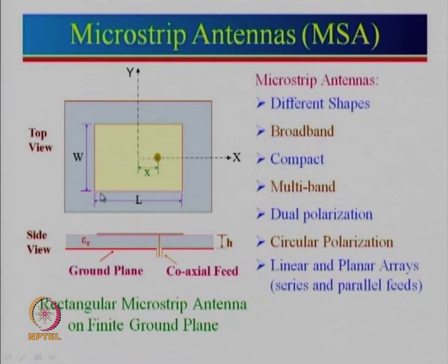and if this length is approximately equal to lambda by 2, now you can see here this is an open circuit, this is an open circuit. So, current will be 0 here, current will be 0 there. So, the field will vary from 0 current to the maximum current and goes to 0, because that is what is making the half waveform. What about the voltage? Voltage will be maximum here, and then voltage will go to 0, and then voltage will go to the minus maxima. So, it will start from plus, go slowly to 0, and then go to minus here. So, if the voltage is maxima, current is 0.